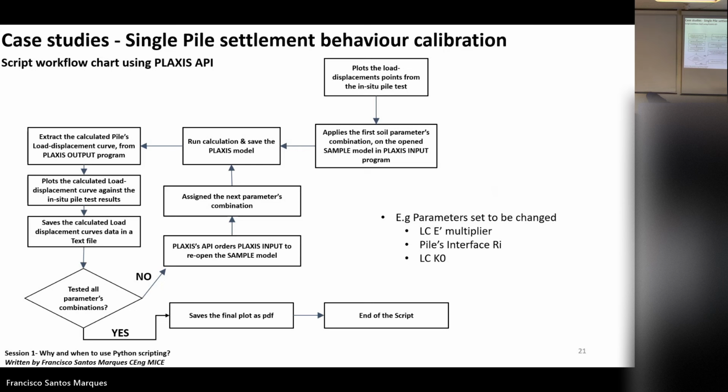By scripting. We still repeat the same tasks: we plot the load displacement curve from the pile test, and we apply a first set of parameters based on our engineering judgment in Plaxis, okay? Let's say we have a simple base reference model in which we set up the geometry in Plaxis input, we run it, then we tell the program to go to the output and extract the load displacement curve automatically.